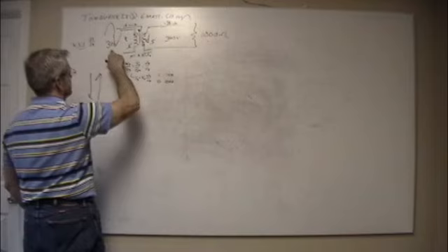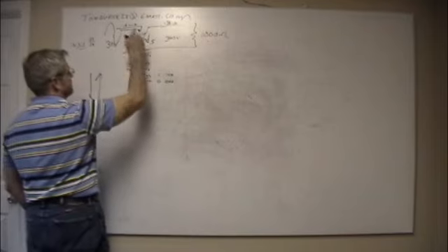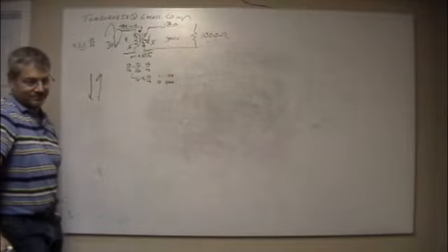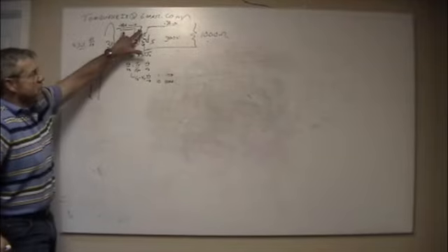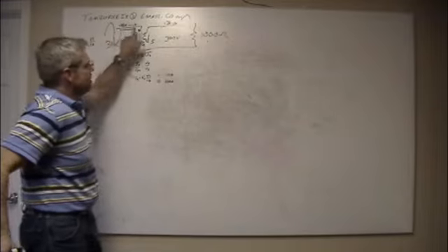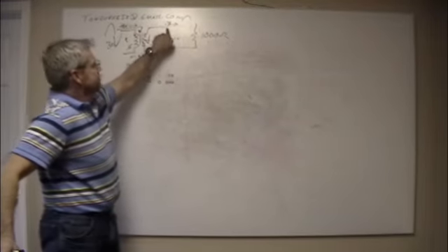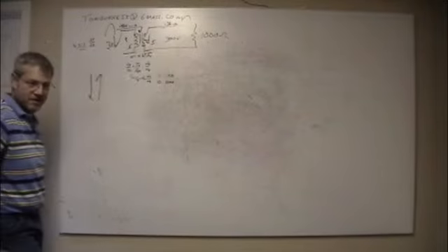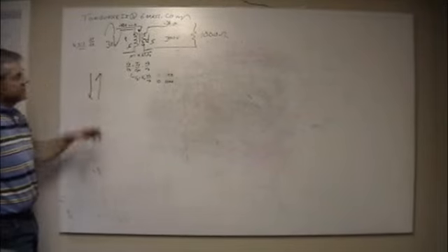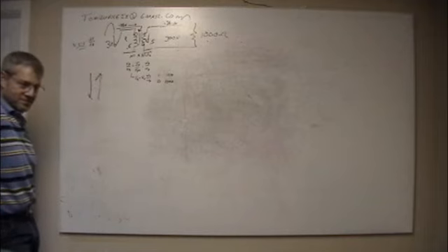But I have to conserve energy. I'm making a mistake here. It should be 1/10. It should be 0.03 amps, because power has to be conserved. 3,000 times 0.03 is 100 watts. 300 times 0.3 is 100 watts.